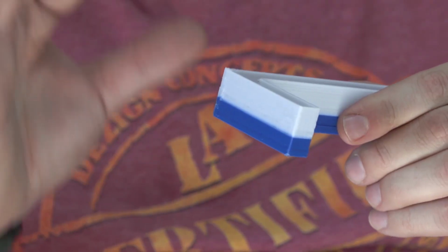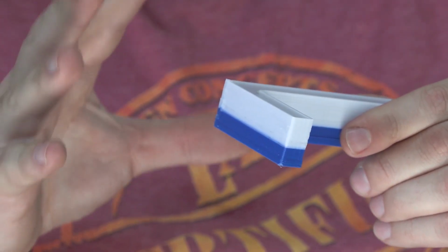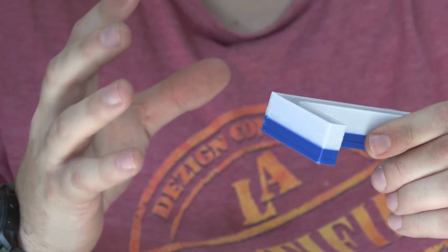So I've gone ahead and taken off our main piece here, and while the top layer is printing, I'm going to go ahead and talk about this so we don't waste any time. If you haven't noticed, there was some excess plastic around the edges and a bit of stringing, which is perfectly normal because that's how the plastic rests as it's moving from position to position. All you're going to need to do is get the supplied clippers or cutters that come with your machine and cut off everything that you don't need, which I've already done, just to show you what it would look like when it's actually finished.